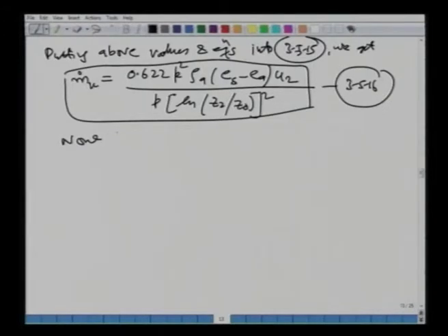However, we still need to find the rate of evaporation. So, what we do is we use the continuity equation, which we have seen already. All right. So, you have m_v dot is equal to what? Is nothing but rho_w times E_A. Okay. And you are saying area is equal to unity. From a per square kilometer or unit area, you are trying to find out what is m_v dot, or E_A is the rate of evaporation from a water body based on the aerodynamic method. So, A here refers to the aerodynamic. Okay. So, if you put this thing in here, you can have